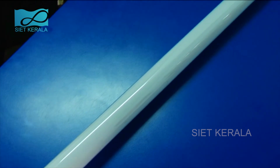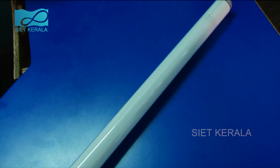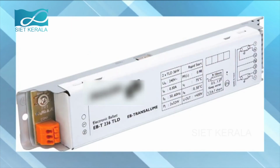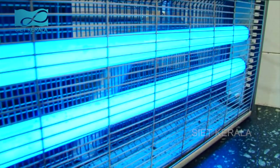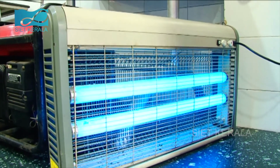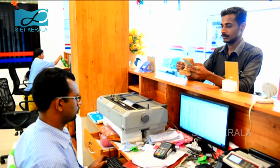A high voltage is always essential for the starting of discharge in fluorescent lamps. It is the electronic ballast that will supply this high voltage. This electronic ballast converts 50 Hz alternating current into high frequency alternating current and supplies it to the lamp. The blue light containing the ultraviolet rays can also be used to trap insects. It is also used in banks to identify fake currency notes.